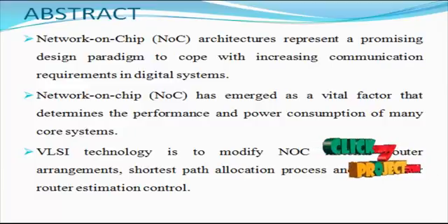The NoC architecture has emerged as a vital factor that determines the performance and power consumption of many-core systems. This paper proposes a hybrid scheme for NoC which aims to obtain low latency and low power consumption. In this hybrid scheme, a novel switching mechanism called virtual circuit switching is proposed to intermingle with circuit switching and packet switching. While traveling, the virtual circuit switching can traverse the router. Based on virtual circuit switching, connections are allowed to share the common physical channel.